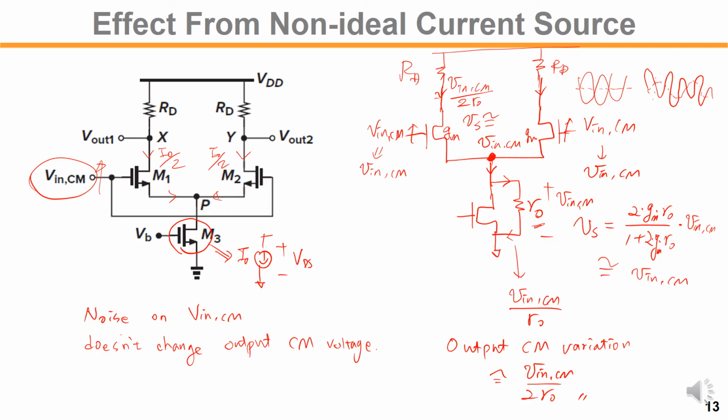Yes, if you look at the difference in the output voltage, you will see the same signal, but the penalty is that you are using up valuable output signal range by the common mode variation.